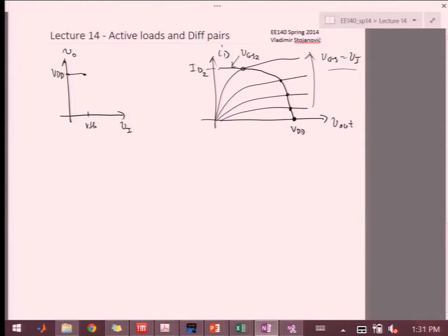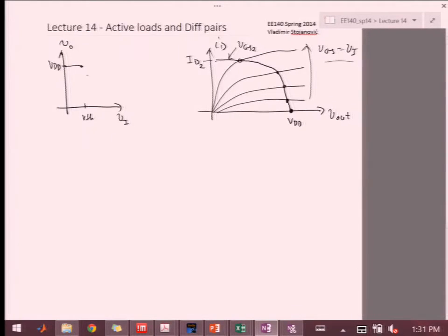And then my V out is at VDD. My V in is at VTH. I have all the conditions to be in saturation. So then I start immediately off in saturation at the bottom device, which is M1. And so I start pulling down.